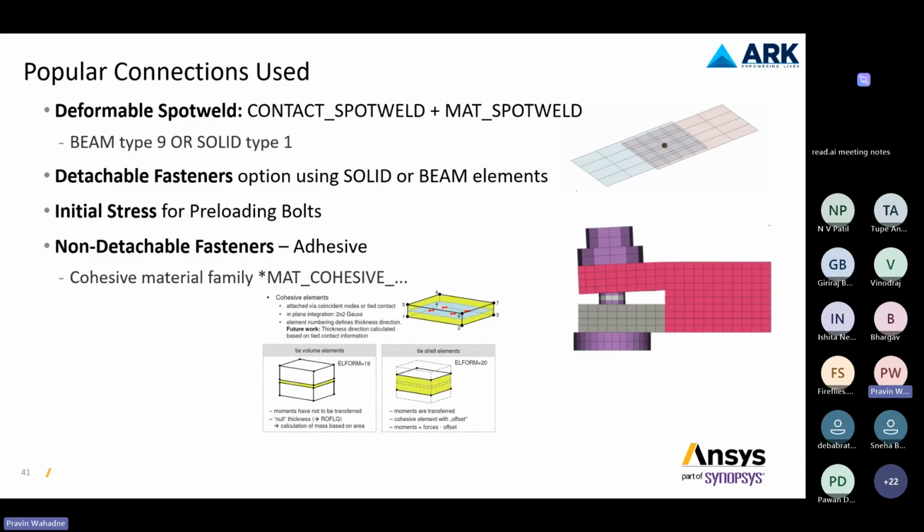Then non-detachable fasteners, which are adhesives, where the cohesive material family is used, like Tiebreak, MAT_COHESIVE. All these popular connections are there in LS-DYNA as compared to other tools.